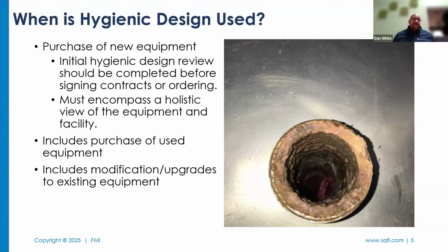So this photo is actually of a piece of pipe that's on a piece of equipment that should have been CIP. However, when they actually added extended lines in their facility to get this piece of equipment washed, they didn't have enough flow in there. And so, I don't know how many months' worth of buildup is inside of that pipe, but that led to product contamination and quite a few issues.